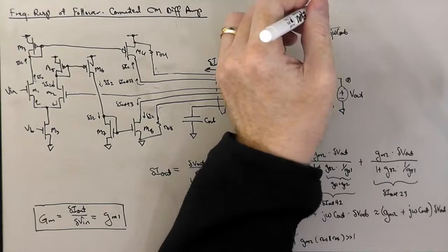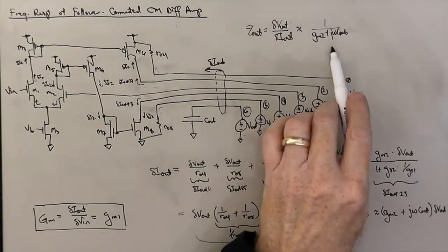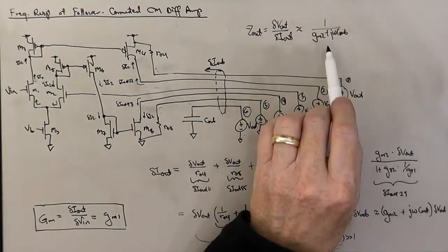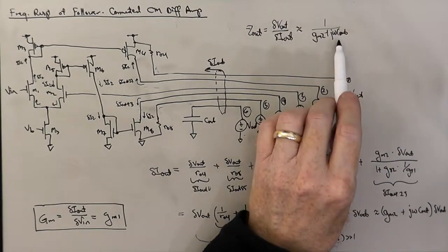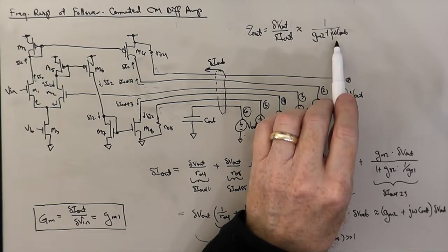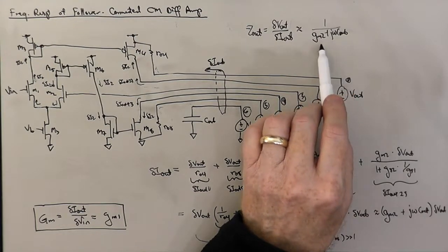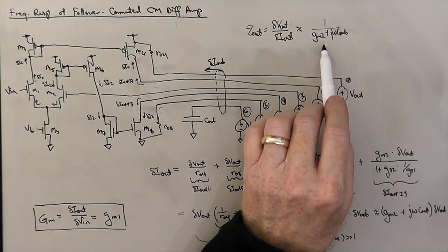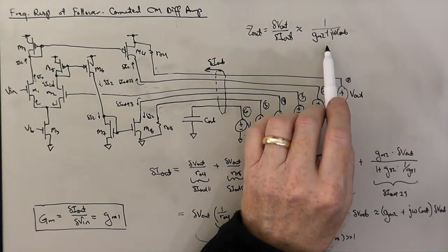which we can, if you like, write in sort of a normalized form. When we have something like this where there's a frequency-dependent admittance, which is the generalization of conductance, like impedance is the generalization of resistance, it's nice if we factor out the real part here and basically normalize that constant coefficient in the polynomial in j omega to unity.